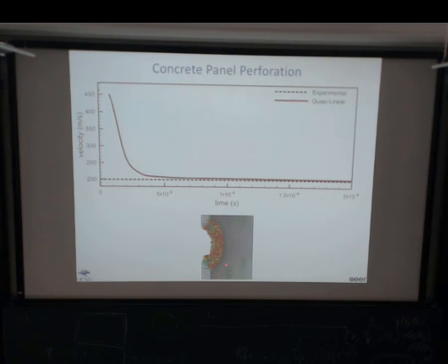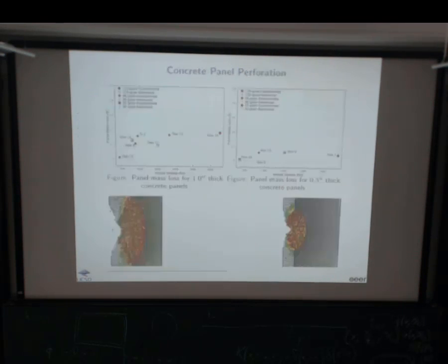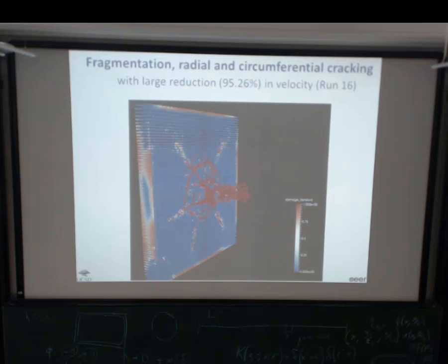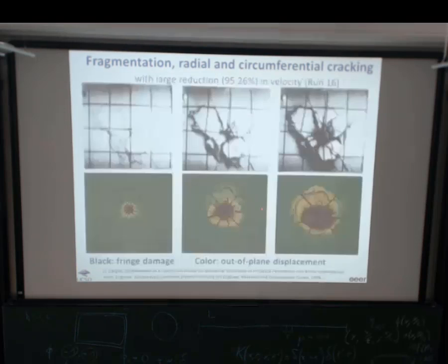The blue curve here is the experimentally measured one. And we also compare the velocity. This is by computation. Experimentally they only measured one velocity, which is the exit velocity of the bullet. But I think eventually computation agrees quite well. Different wall thickness, different fracture pattern. And now you can model this, properly capturing all the radial cracks and the circumferential cracks. Not perfect, impossible, right? Because the material has so much variation, but this is experiment, and this is by computation.